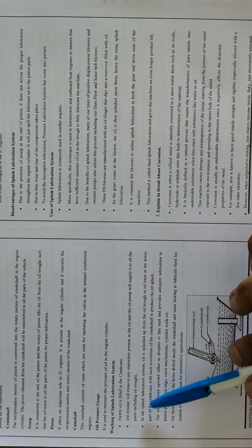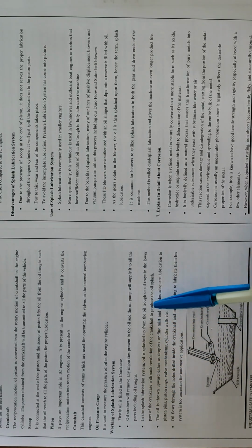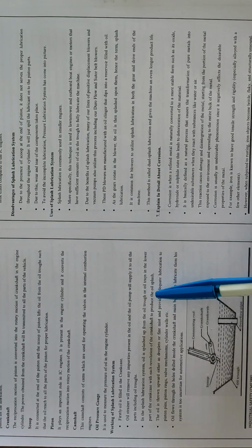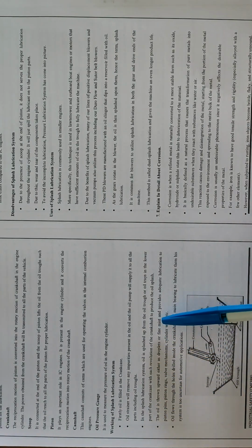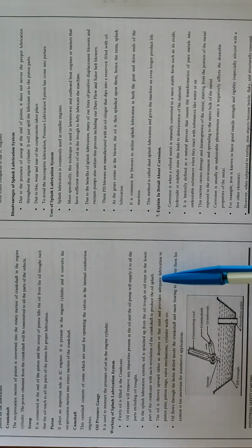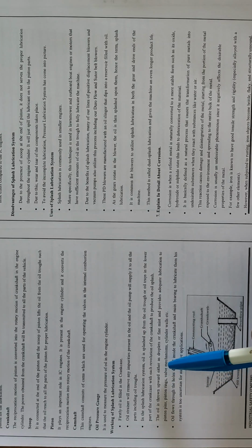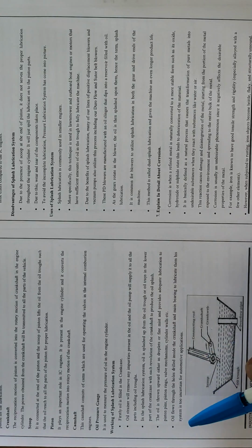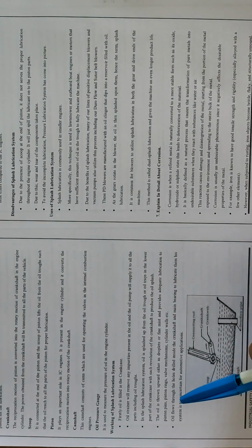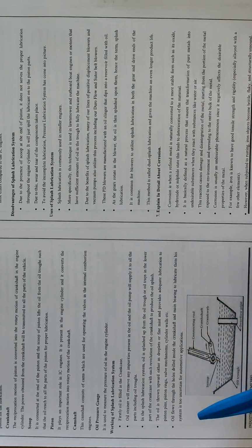including oil troughs. In the splash lubrication system, oil is splashed from the oil trough or oil tray in the lower part of the crankcase with each revolution of the crankshaft to produce the oil splash. The oil is thrown upward either as droplets or fine mist and provides adequate lubrication to piston pins, piston rings, valve mechanism, cylinder walls, etc.